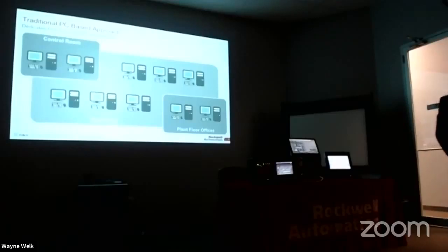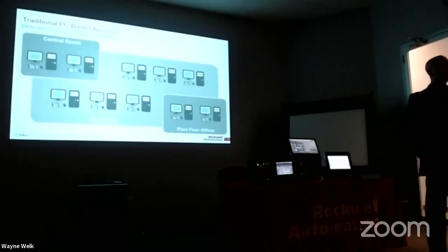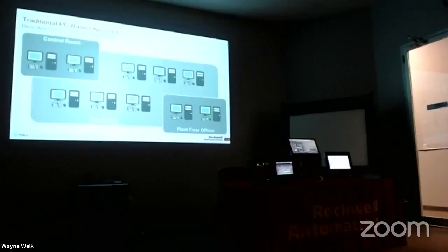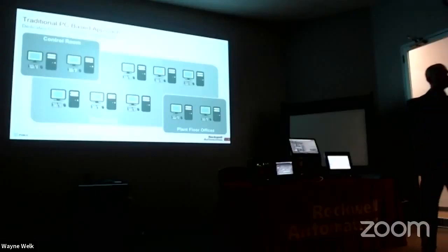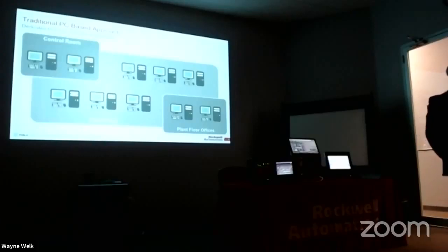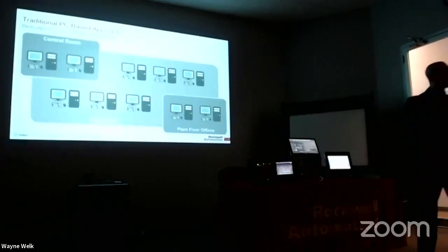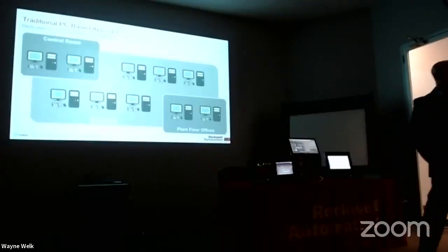Pre-execution environment, PXE boot. But there also is another way of doing that. And Chris talked briefly about it. And that is what I'm going to call a Rockwell Thin Manager Ready unit. What does that mean? It means the BIOS is already in the device. What you have to do is physically go plug in a mouse and keyboard, what have you, get in there, go into the BIOS, change the IP address to be static. So if you want to manage your IP addresses, you can do that.